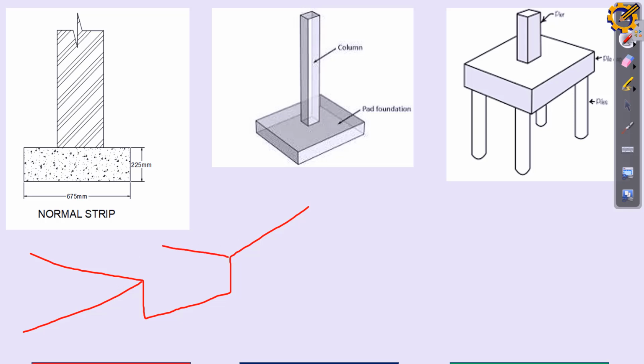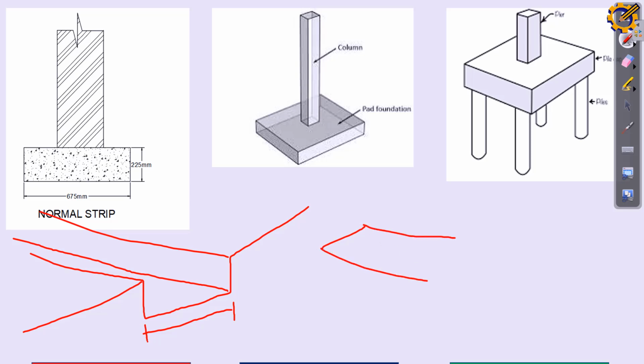So this is my soil. I've excavated. The gap from this place to this place that I excavated is going to be 675. A typical block, the block you call a 9 inches block, what is its thickness? It is 225 mm.